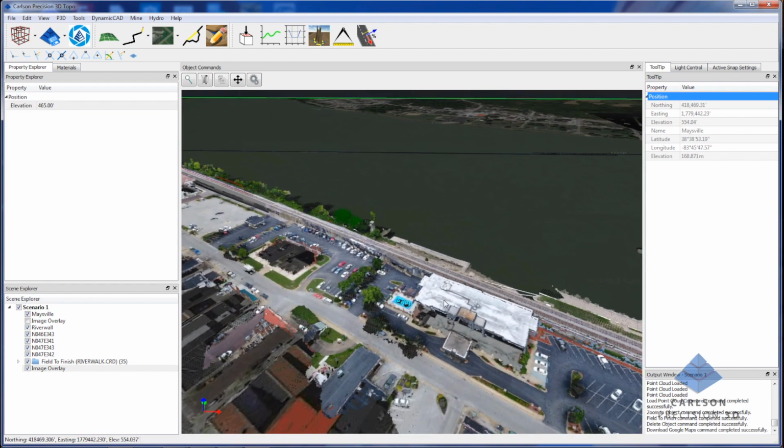But that highlights some of our new point cloud loading, so we can load up to 50 files simultaneously while maximizing every bit of compute horsepower that your machine has, the number of cores you have and the amount of RAM that you have. So if you have 12 cores but you only have 16 gigs of memory, you're going to be memory bound.